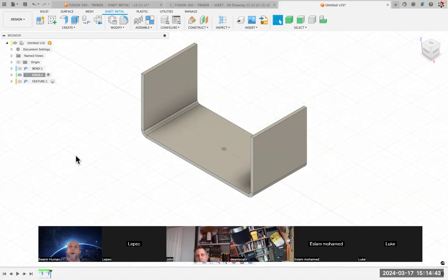Yes, good question. Because most CNC machines that are doing the sheet metal cutting, you'll typically have a plasma cutter, or you can have a laser, but they generally just have a vertical motion up and down. They don't tilt. I mean, you could have one, but that's more advanced. Typically, you're just cutting straight down through the material. So in this case, we should just cut the metal as is instead of unfolding? No, because then it won't be in the right place and it won't make a flat pattern. You'll be violating the rules and the reality.